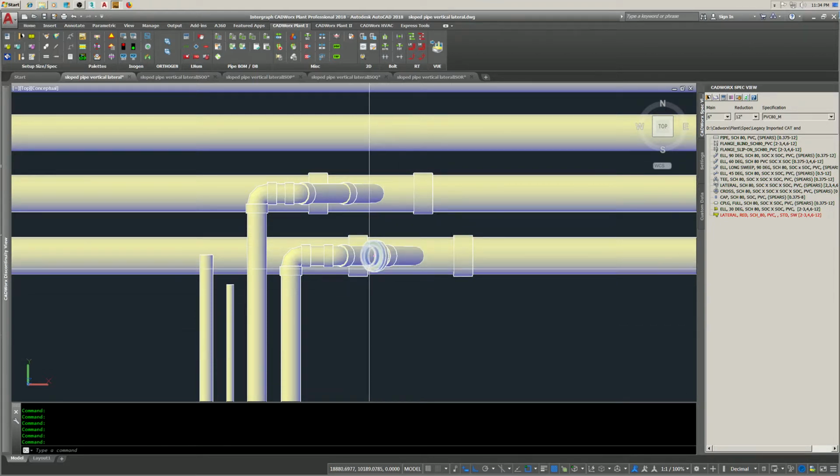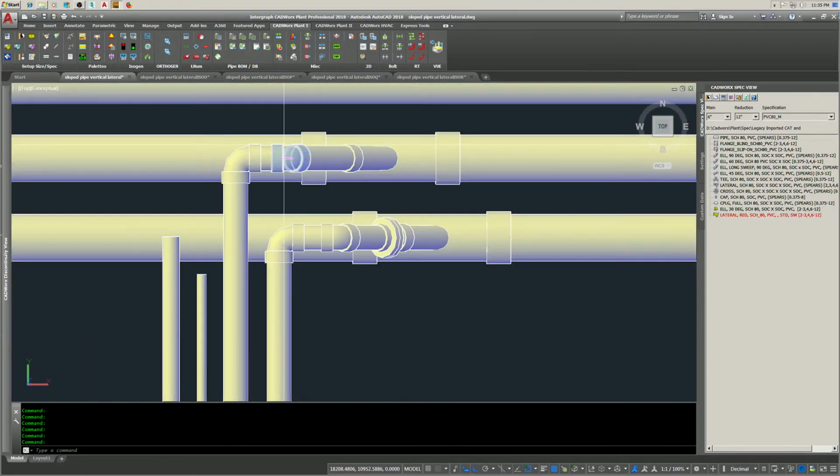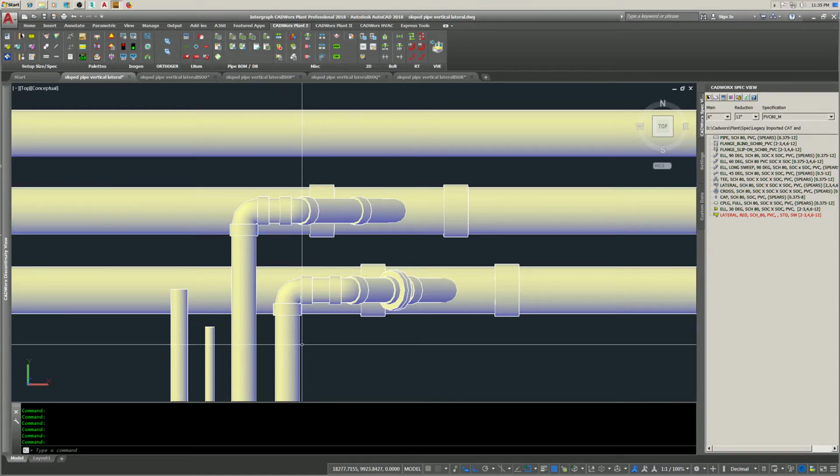This arrangement allows, first of all, a little wiggle room for constructability for the contractor. Plus, if you want to bring a line off going north, this is south, rotate the fitting 180 degrees and then adjust the angle for the slope.